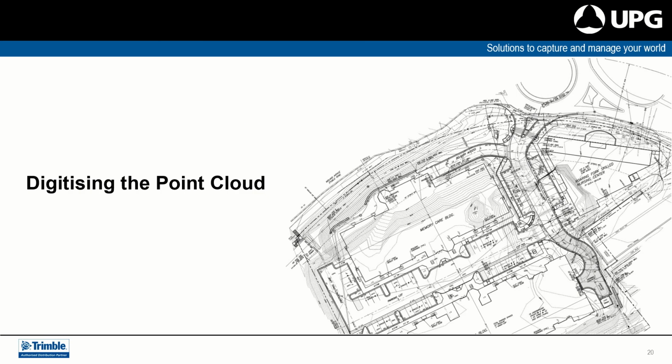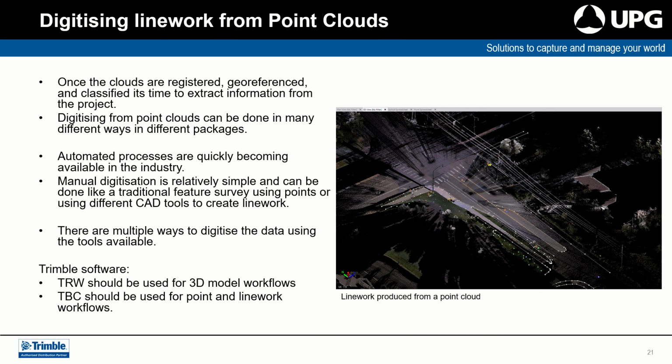There are several tools also for digitizing the point cloud. When digitizing the point cloud, we can use many different techniques. The very basic technique for digitizing the point cloud is actually coming from, say, SX10 data or SX series data, where it's captured in the field from the instrument itself as a total station point that comes in and is overlaid against your scan data, which can then be used for digitizing. This is the easiest way of doing it. It's using field practices, and it's just overlaying the data to scan data.